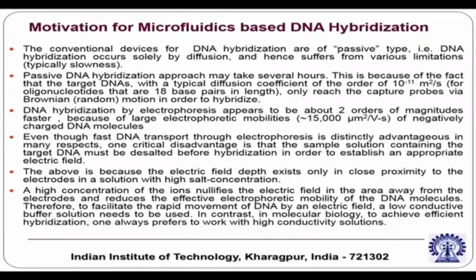Now you know that diffusion is a slow process, it will take several hours if not days to complete the hybridization process, and the typical diffusion coefficient is of the order of 10 to the power minus 11 meter square per second for oligonucleotides that are of 18 base pairs in length. And then in a pure diffusive environment the DNA will reach the capture probes only by Brownian motion in order to hybridize. What is an alternative?